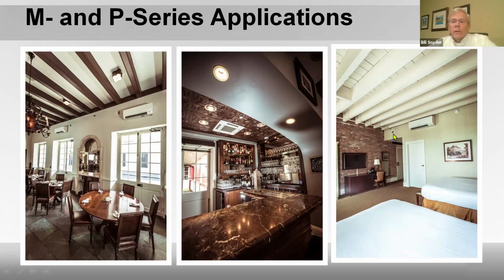Or even in here, that looks like a little vent or an exit sign, I'm not too sure. You could put above this wall an air handler, like the PEAD type air handler, and just blow it right out into the room. So I'm not sure this is the best application. It's kind of open around the beam, so it probably works, but I would not have done this. To me, that's not that great of an application.